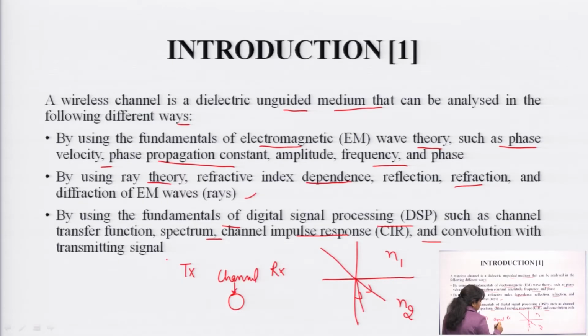There will be AWGN noise, because in this communication we consider AWGN noise most of the time. When we do the mathematical analysis of this noise, its transformation and inverse transformation are the same. It is like a Gaussian function and it is additive in nature. That is why we can easily do the mathematical representation of this noise. Its power spectral density, PSD, is constant from minus infinity to infinity, denoted by N0/2. So, this is the transmitter, this is the receiver.